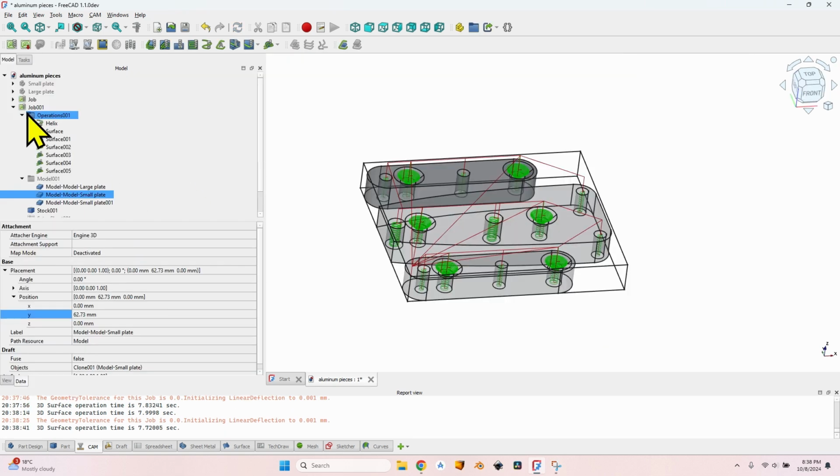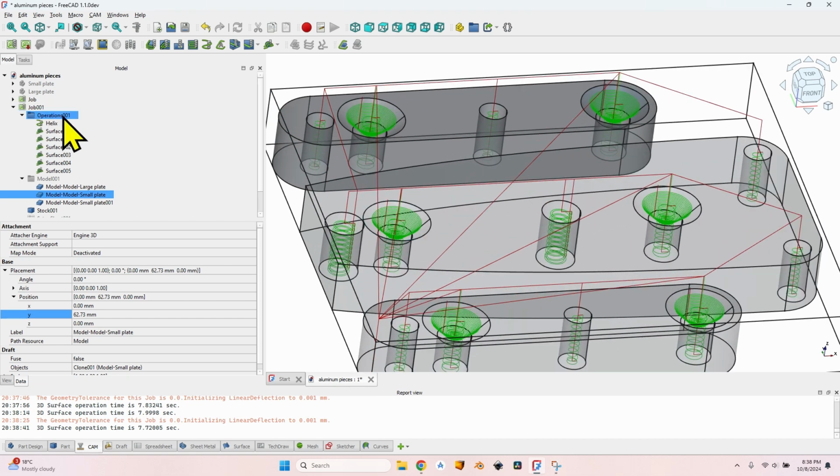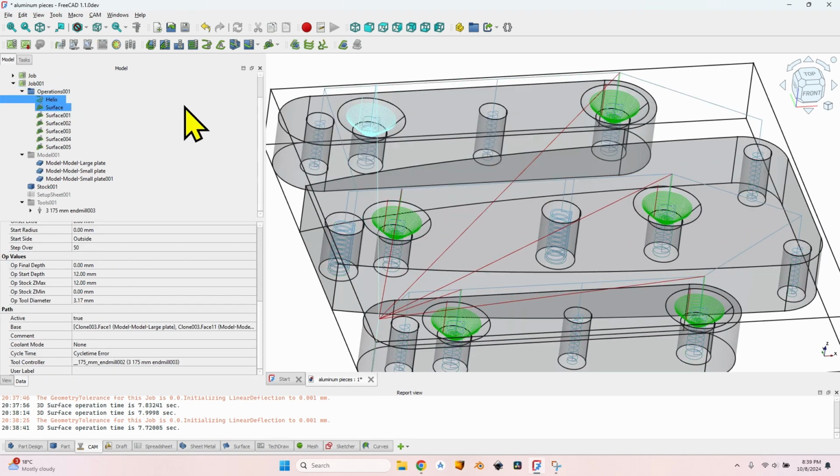And now that I have everything ready for milling the holes, for making these chamfers, I know you might say that it's a waste of time, but after setting the speeds for the toolbit, after taking into account the machine, the material, the toolbit, and setting their speeds, I will show you how much these surface operations take. But I can tell you from now that it will take a maximum of 2 minutes to gather all these 6 holes. So stopping the job, changing the toolbit, resetting the Z value, then changing back again the toolbit to get an end mill to cut the outlines would mean much more time.